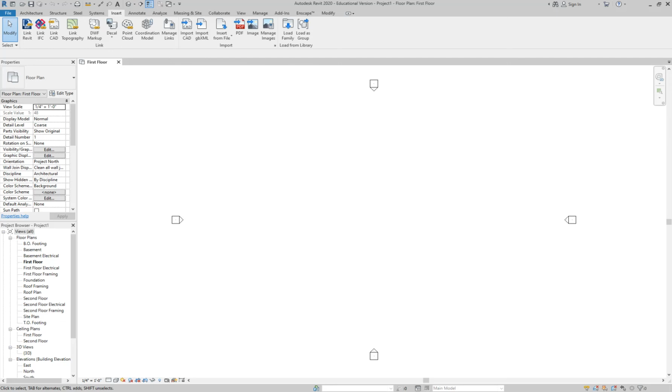Now, I'm assuming that most of you will be a one and done. I figure if you are doing editing, you may as well do it in Revit or print it out and just kind of draft on top of it, okay? But I wanted to let you know that option is available. You might be working with an architect or a client who's working in AutoCAD, and you are in Revit. That's also common. I've had to do that before where we're kind of speaking two different languages. So that's the difference between the two of them. Linking gets updated. Import is kind of a one and done, all right?